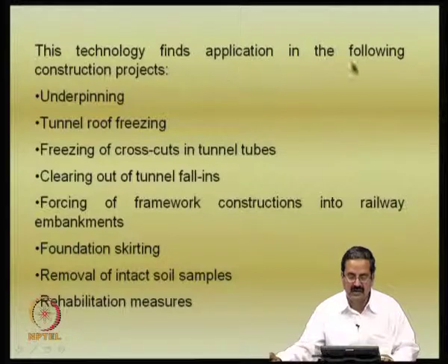This technology finds application in the following construction projects: underpinning, like keeping that in a stable condition, tunnel roof freezing, freezing of the cross cuts in tunnel tubes, clearing out of tunnel fall-ins, forcing of framework constructions into railway embankment, foundation skirting, removal of intact soil samples.